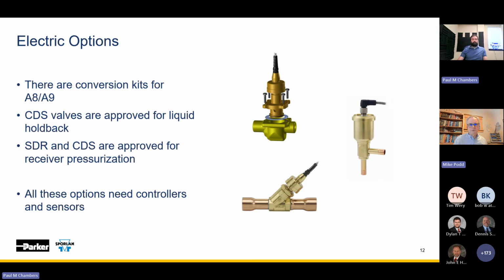Yeah. Again, also more things to go wrong. So you've got the communications and your sensors and your other devices too. But yeah, there's benefits there. Again, you could shut this valve off remotely if it was bypassing and it shouldn't be. There's that capability. So you can shut this valve off remotely, but it might not have the same zero positions of a mechanical valve if you lose power. Yep. So pros, cons, both sides.